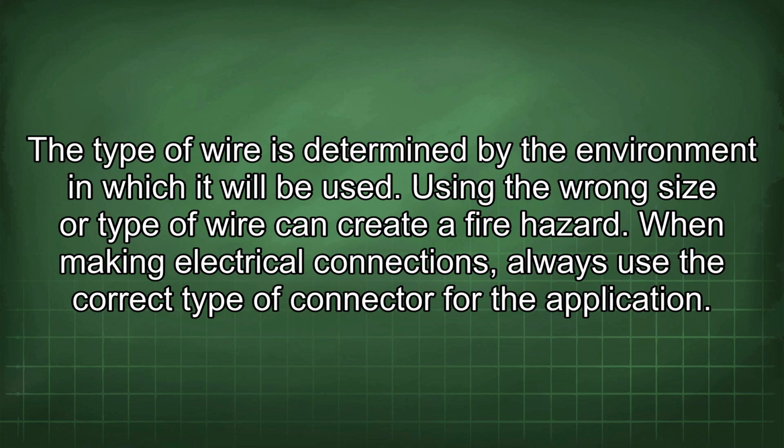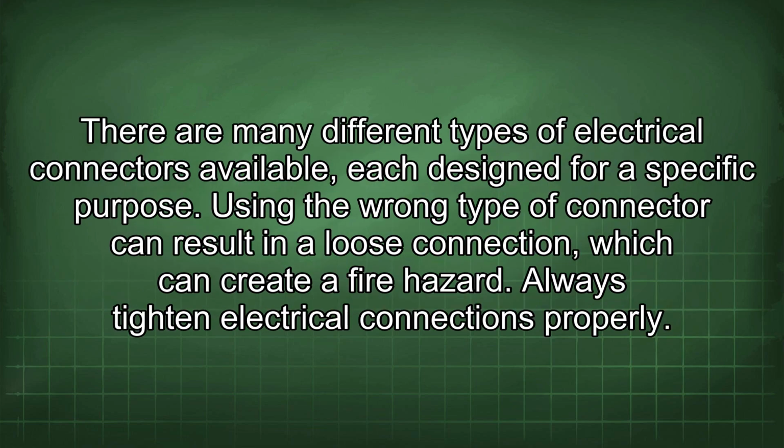When making electrical connections, always use the correct type of connector for the application. There are many different types of electrical connectors available, each designed for a specific purpose. Using the wrong type of connector can result in a loose connection, which can create a fire hazard.